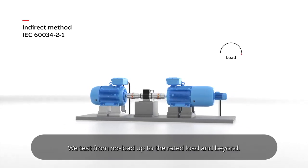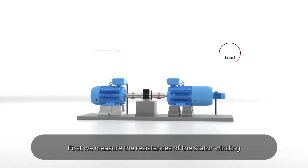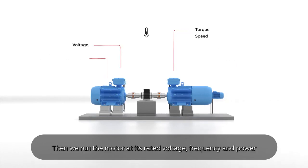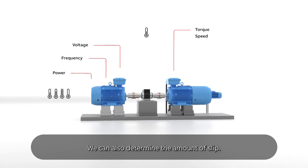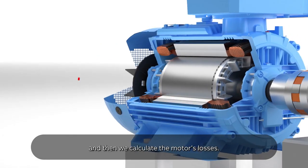We test from no load up to the rated load and beyond. First, we measure the resistances of the stator winding at ambient temperature. Then we run the motor at its rated voltage, frequency and power until all the temperatures have stabilized. This enables us to calculate the motor's temperature rise. We can also determine the amount of slip. We make the required measurements, collect the data, and then we calculate the motor's losses.